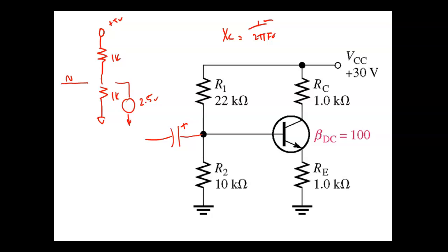So every audio amplifier has what we call a bandwidth. And what's the bandwidth? We talked about that the other day, right? The range of frequencies passed. And what happens if the frequency gets too high, it starts jumping across these junctions, and we lose control of it too. So the transistor sets the upper limit, and then your input, or coupling capacitor sets your lower band.